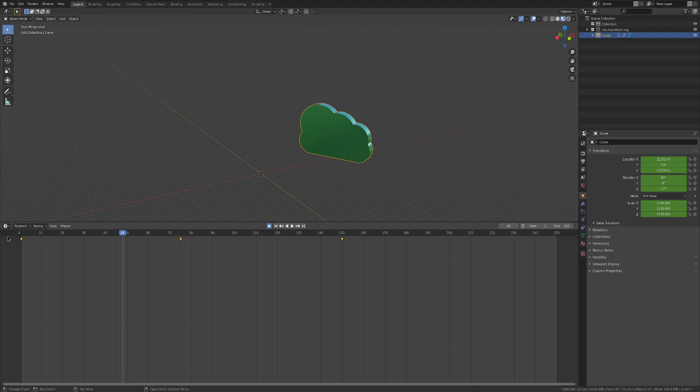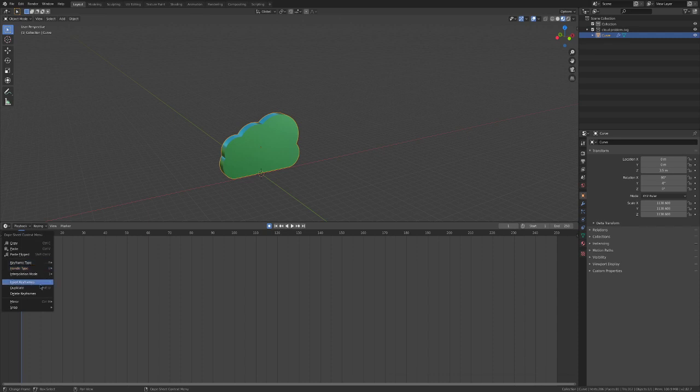Otherwise, let's remove the keyframe. I select them and just delete keyframe. First of all, you will stay in the position of the keyframe, of the frame you were in that moment. Let's put it in the center again. Let's put it 0. This one 0. So in theory, I can go here with this activated. I can say, okay, insert keyframe. Sorry, I'm going to the first frame, and I insert keyframe.